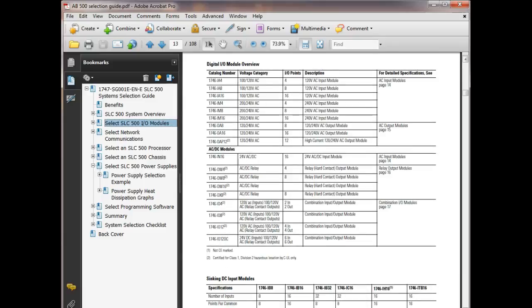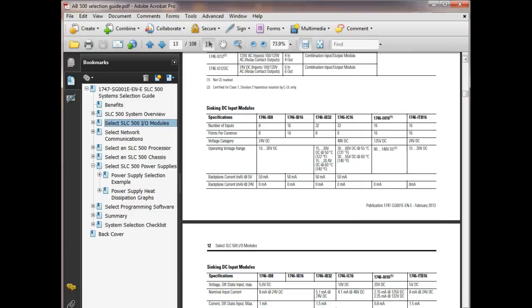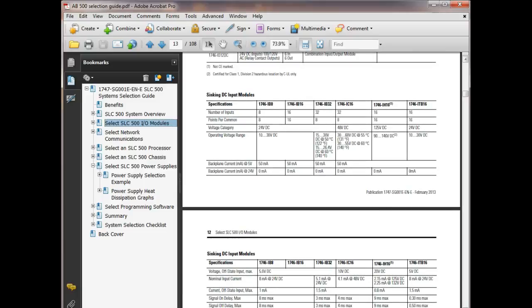And these are AC modules. So you can see they come in and then they split them up and actually give you the syncing modules, each one by themselves, and then they give you the electrical characteristics of the thing. So these are all syncing. These two run on 24 volts. These three run on 24 volts. This one runs off 48 volts. This is 125 volts. This is 24. I'll tell you how much current they pull, right? Backplane current, backplane.